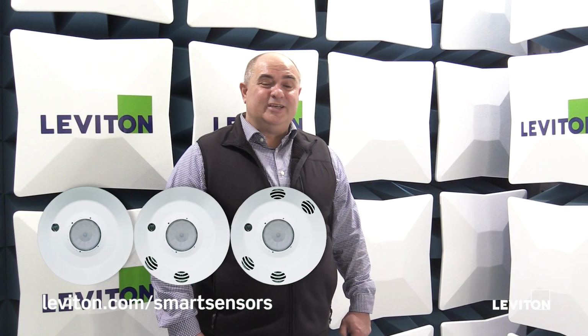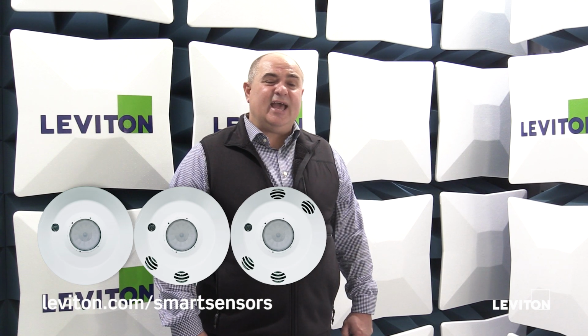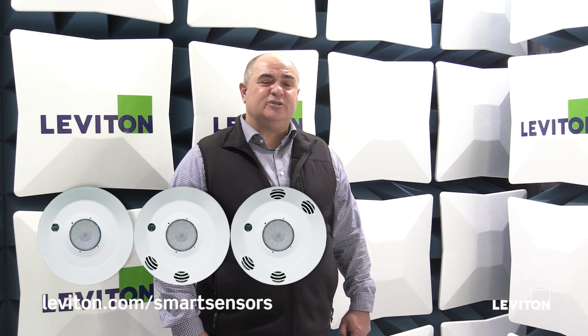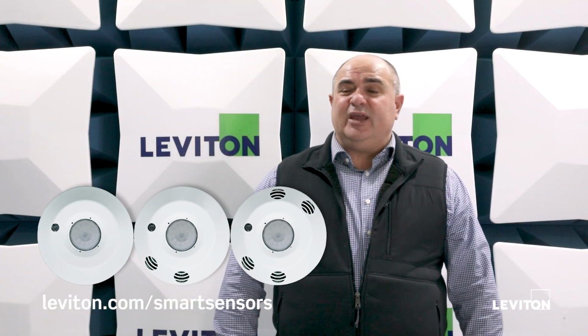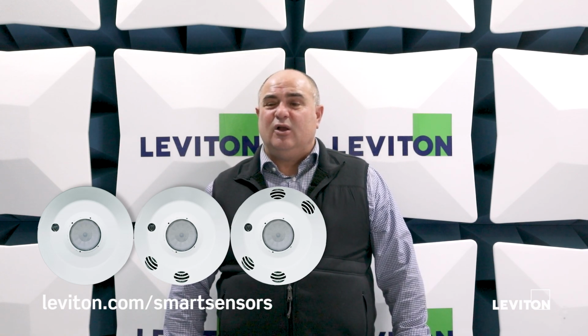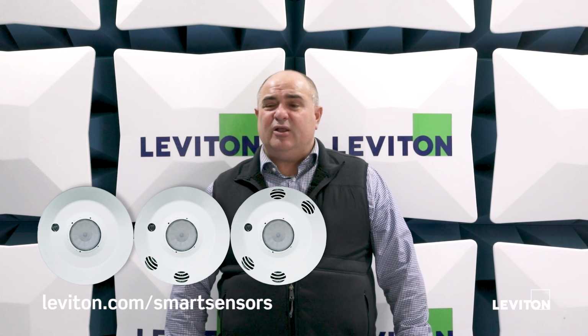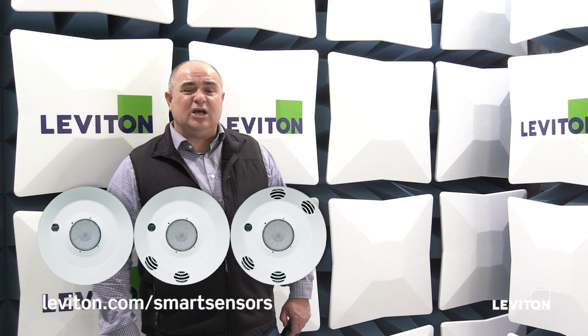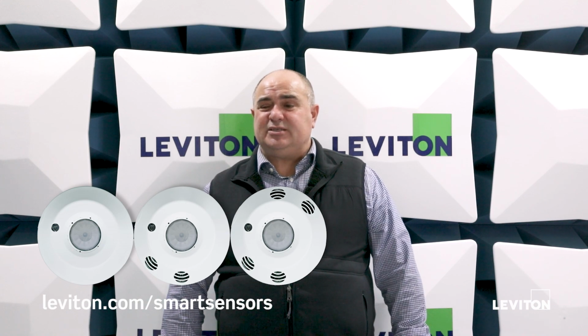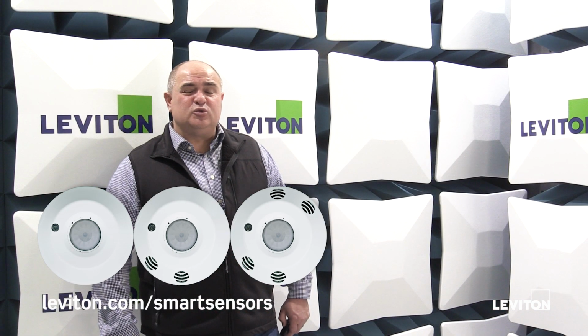Number 1, we definitely need to understand that this can in fact be used to comply with all 3 of the major energy codes: IECC, ASHRAE 90.1, as well as Title 24. The other thing that we need to keep in mind is this device is actually an integrated occupancy sensor or vacancy sensor, photocell, and power pack, all in a self-contained device. The other feature is that it's completely standalone, networkable, as well as wireless, in its ability to be used within the space.